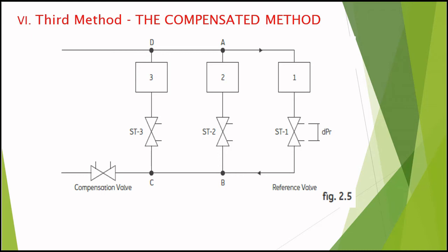And to achieve this, it is necessary to continuously monitor the differential pressure of the valve already set up and, step by step, cancel the changes caused by setting the others by throttling a balancing valve, the compensation valve installed upstream of the circuit.